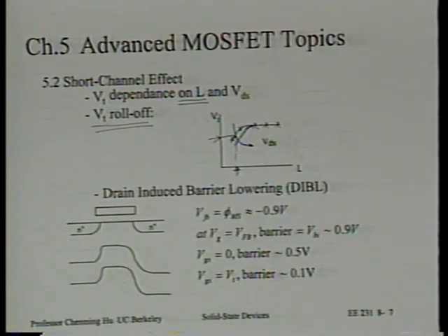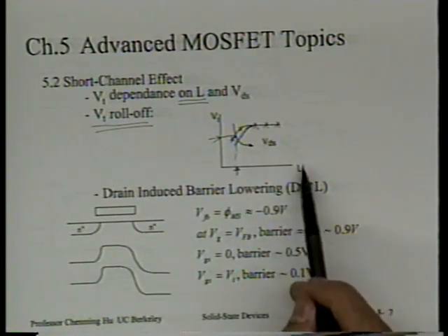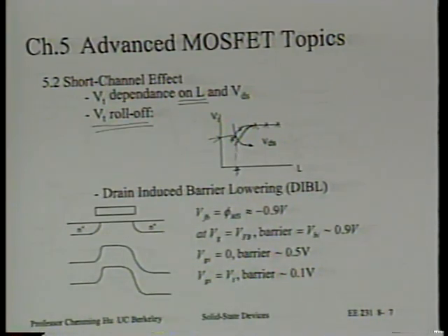We do things like etching of the photoresist pattern. By putting the photoresist pattern in a plasma, oxygen plasma, we can actually make the photoresist pattern thinner. As a result, we can actually beat the optical diffraction limit of the lithography machine. So we're still then limited by the device physics, which will be this problem. All right? Okay, so this is definitely a real limit.